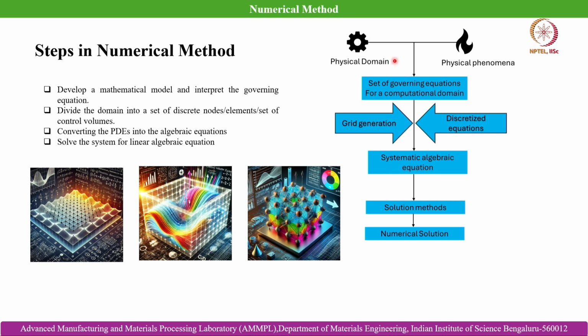So basically it is a combination of physical domain and physical phenomena that we are trying to resolve by developing numerical models. The concerned set of governing equations which are applicable in that given computational domain, we identify those, and then we discretize the domain, we generate the grid, and then we arrive at the set of algebraic equations which give approximate solutions to the PDEs.